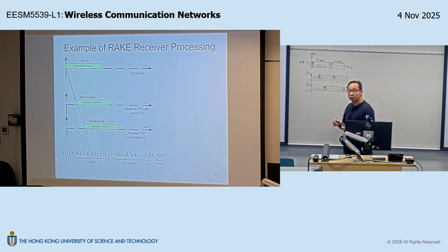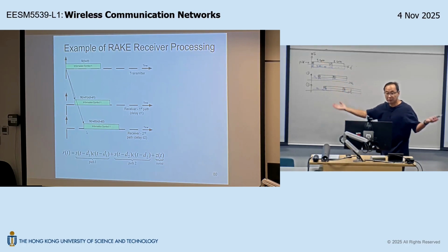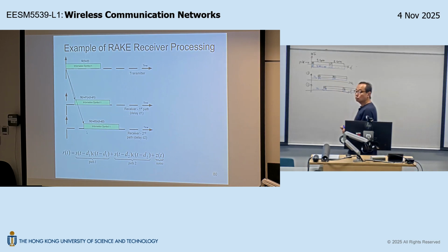So what you do is you first try to despread the pilot channel. You know the spreading sequence for the pilot channel as well. This is defined in the standard, and will be the same in all base stations. So how do you despread the pilot channel? You know the despreading sequence, CPT, but you don't know the despreading timing. But fortunately, because the pilot channel is periodic, you only have finitely many possible despreading timings. So let's try to do an exhaustive search. What do I mean?